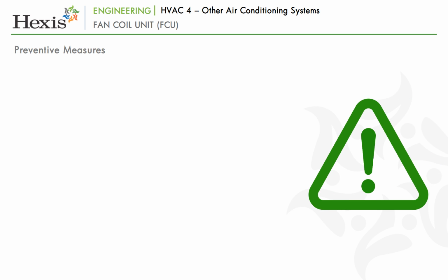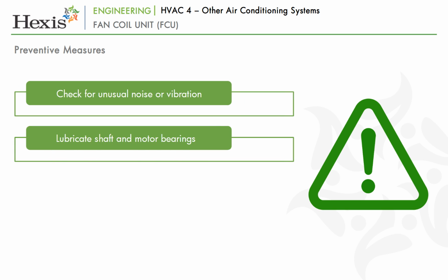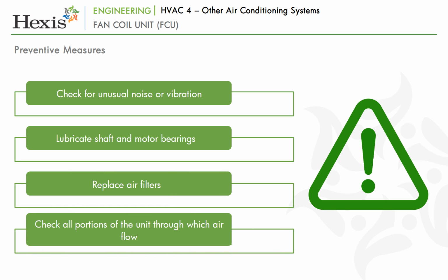Let us study the preventive measures to be followed while using FCU. Check for unusual noise or vibration. Lubricate shaft and motor bearings. Replace air filters. Check all portions of the unit through which air flows.